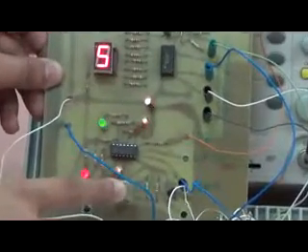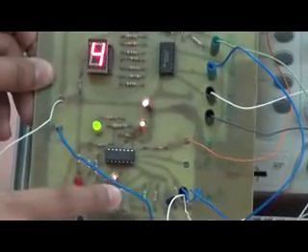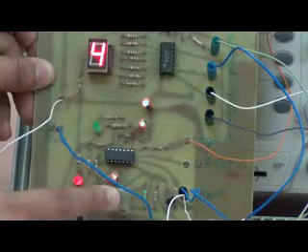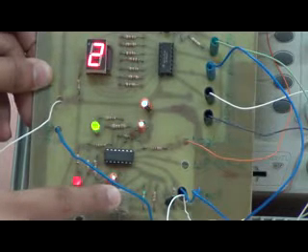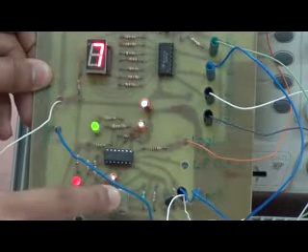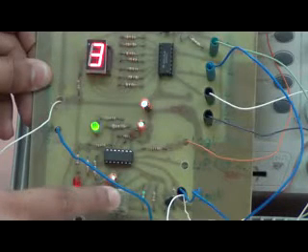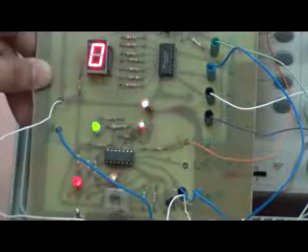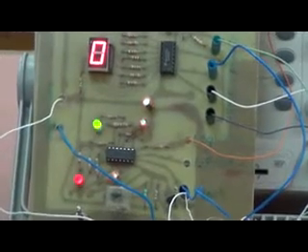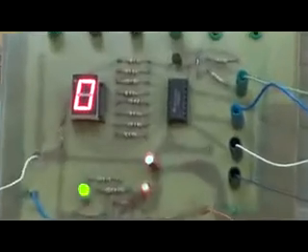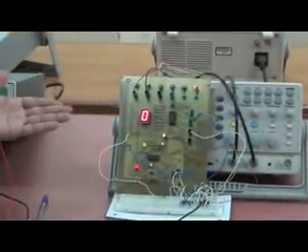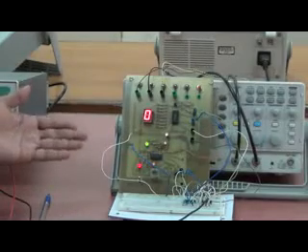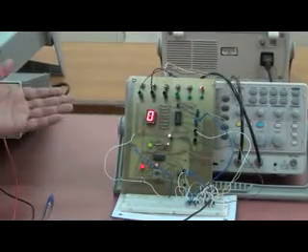Now I will manually give a pulse to the counter. So the state is being changed from 5 to 4. Again I have pressed it and it's displaying 3, 2, 1, 0, 7, 6, 5, 4, 3, 2, 1, 0. So we can see that manually also we can control the sequencing of this counter. We need not give the clock to it directly from the digital test board. We can manually control the output of this counter by using the manual mode of this digital test board as per our convenience.